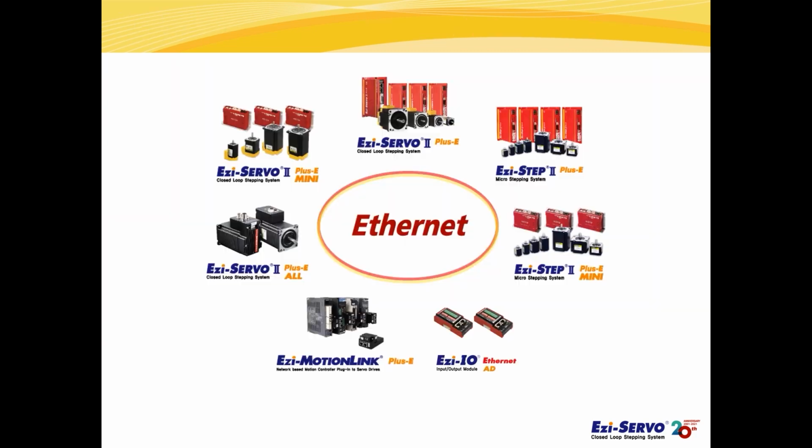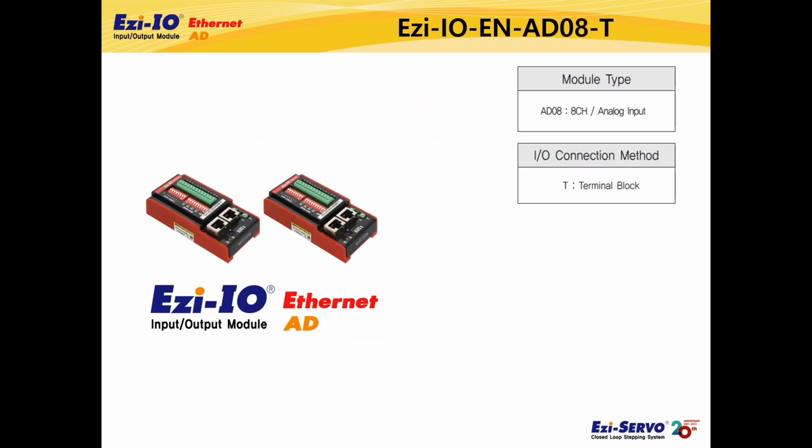The next product to be introduced is Ezi-IO Ethernet AD, an Ethernet-based analog input module. First of all, I will explain the combination model name of the Ezi-IO Ethernet AD product. In the example model name, I/O means input and output module, and EN means the product uses the Ethernet network. AD08 means that the product supports 8 analog input channels, and T means that a terminal block is applied. Now let's check the features of Ezi-IO Ethernet AD products.